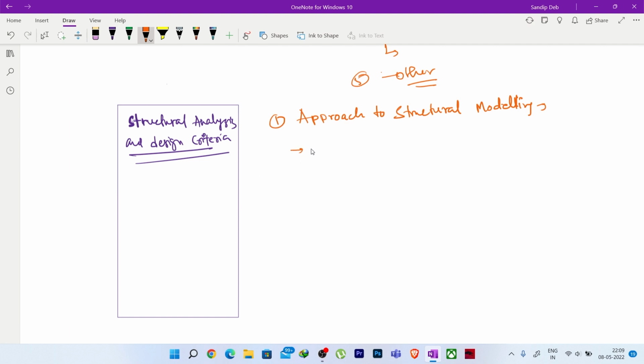Suppose you have considered the beams and slabs as lines. Okay, you have added the walls and slabs as shell. Next, maybe the sunken slabs are not modeled, but the loading is assigned for the sunken slab, so you can write this also. The inverted beams, maybe the inverted beams are not modeled as inverted, but it will be considered while designing it.